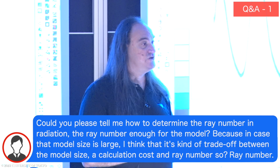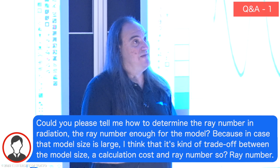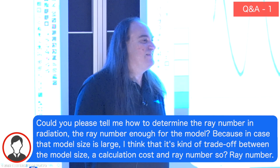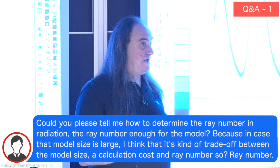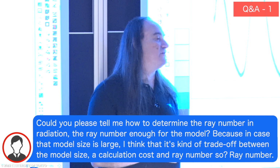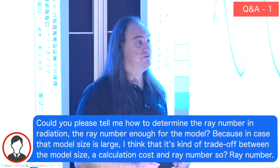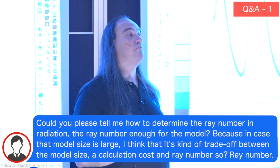But early on, as you're flushing out your design and you're running your models, it's good to do a sensitivity check and really say, okay, I ran this with 3 million rays, the temperature differences were 1/10 of a Kelvin. It doesn't matter. But okay, with 3 million rays on this cryo region, it was a 5K difference. That area I might want to pay a little more attention to. So it is very problem specific.